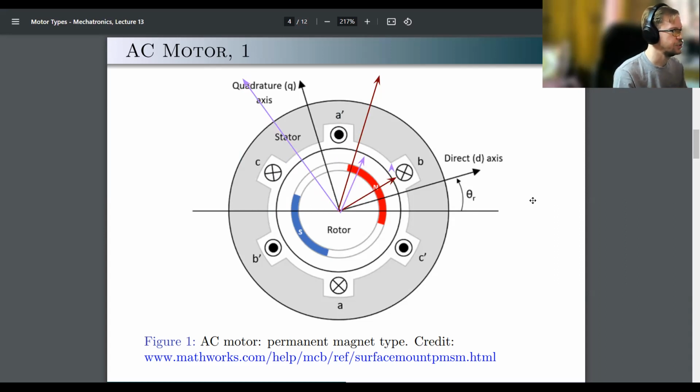because your wall electricity has 60 hertz. So it means 60 times a second it completes this full period of a sine wave. So in 60 times a second, it would go all around your motor, this magnetic field. Again, this depends on how you wire your motor. You can do it differently, but it's a rough idea. So you rotate your magnetic field simply by using wall electricity.